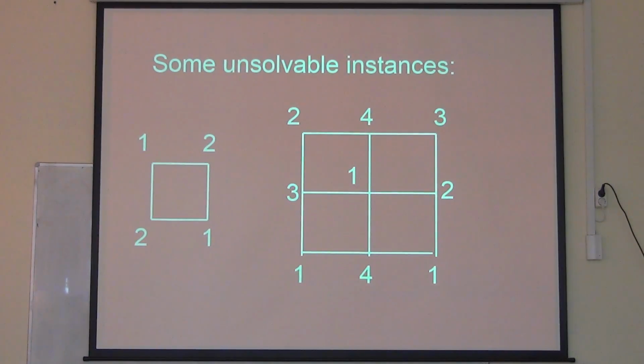Then obviously you can't solve that, because you start going from this terminal upwards, orthogonal to the basic plane, and in the very moment when you turn to the right or to the south, you will block one of the terminals of the second net. So if you don't have an extra column or row, then again you can't solve that. A similar but somewhat more complicated situation is here.